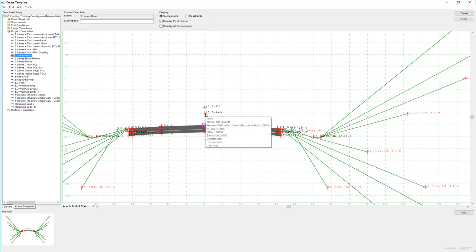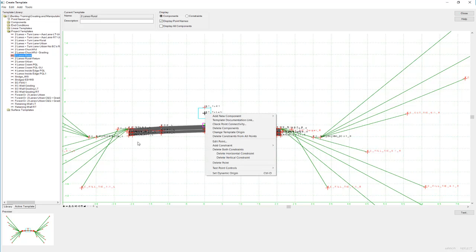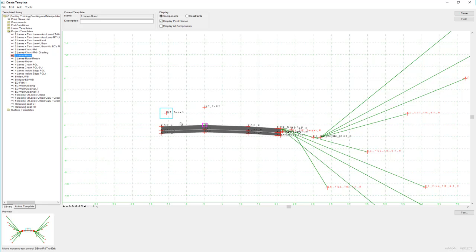Same thing applies to the point on the left. If this point can find that match line feature definition from the element that we added to the corridor as a corridor reference, when we test that, it'll move to that location and then it'll automatically turn off the shoulder and the grading. So this is just one way that you can handle those intersection areas if you need to do this kind of thing.